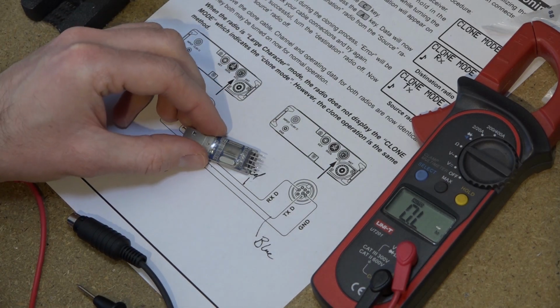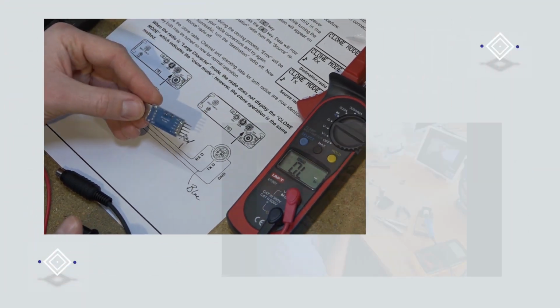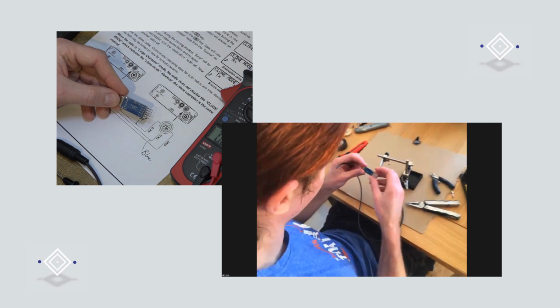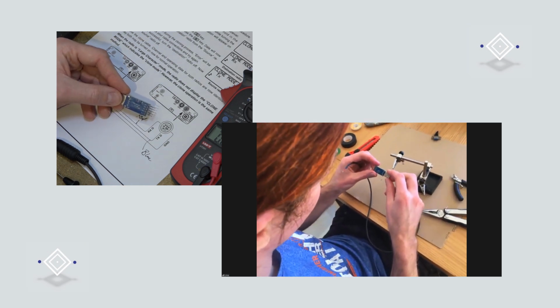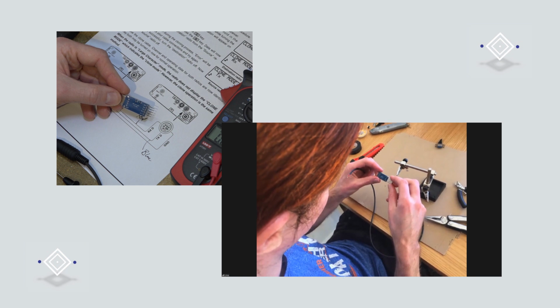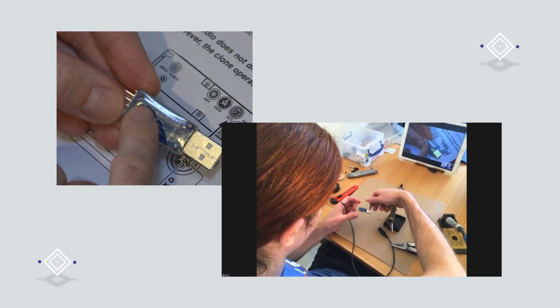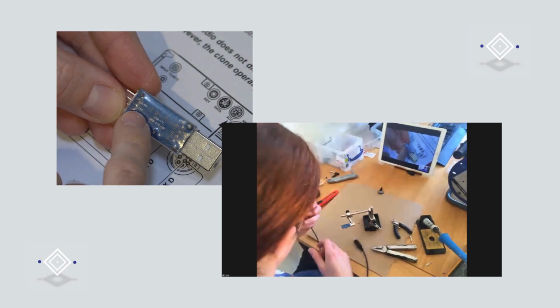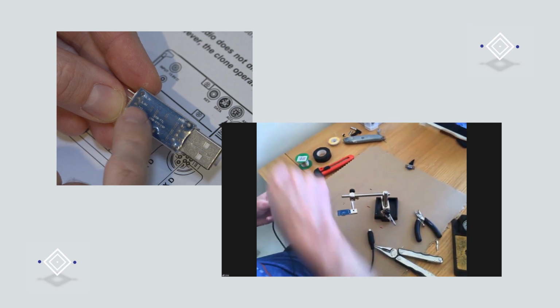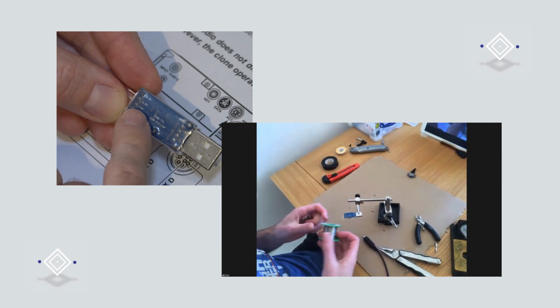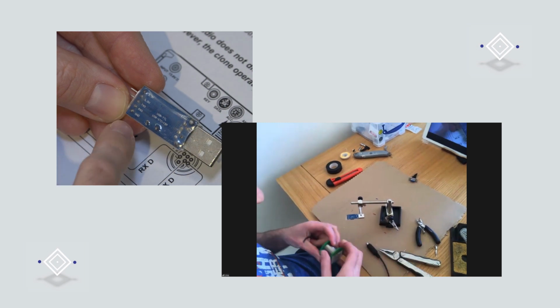So I take it we're now attaching this. We are. You've now got your USB to serial converter. And if you have a look on the bottom of that, you will find some labels. Oh yeah, TXD, RXD and ground. So yeah, we've got on here 3 volts, 5 volts, transmit, receive, and ground. We don't need to worry about the 3.3 and 5 volt pins for this. Just going to need the other ones.